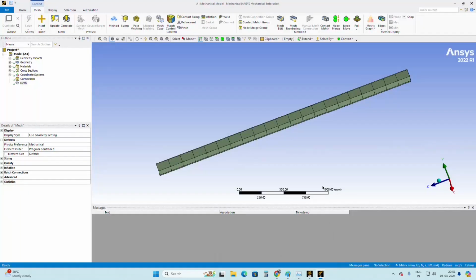In today's class I just demonstrated how to create a 3D structure in SpaceClaim, how to convert that solid element into one dimensional geometry, and then how to calculate the shear force and bending moment diagram. As well as I explained that even if you are creating multiple joints or multiple beams, you should give the share option, otherwise you won't get proper results.